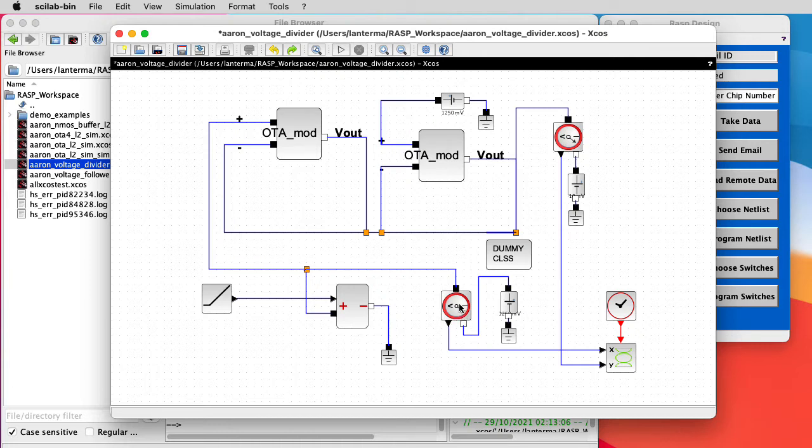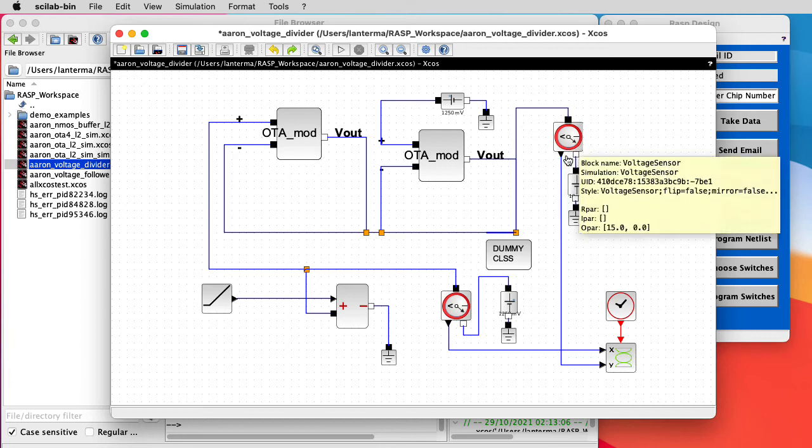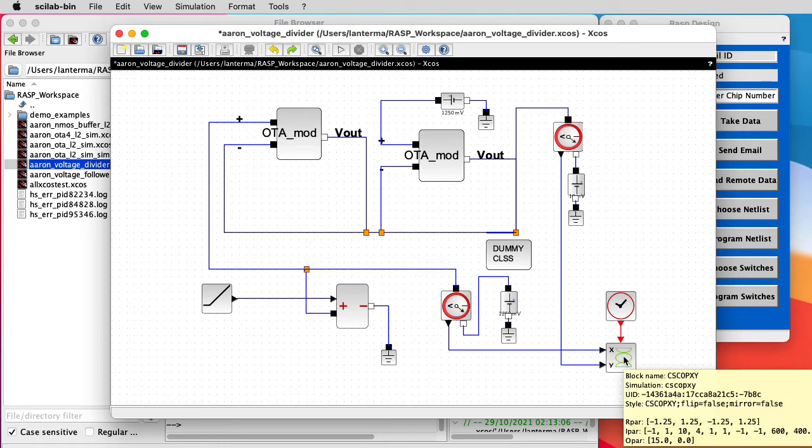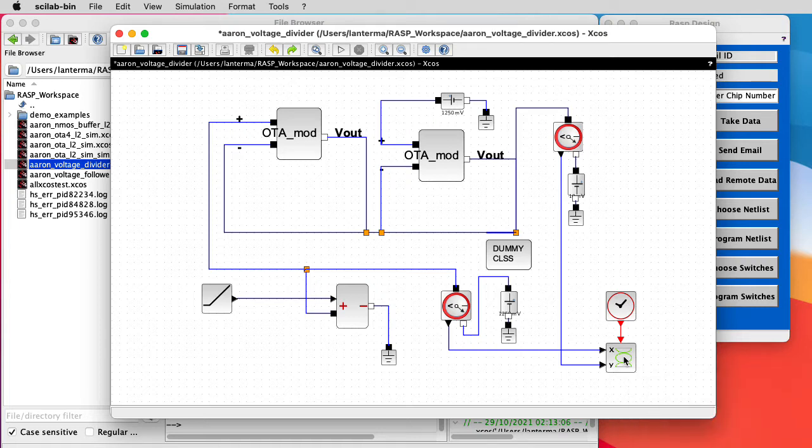Anyway, I have one of these voltage mechanisms for the input and another voltage mechanism for the output, both referenced to that 1.25 volts. So if the voltages here are 1.25 volts, that then is going to show up as 0 on the scope. And I did that just so my plots are all centered at 0. I found that an easier way to interpret the input-output transfer function. Here I mean just the nonlinearity of whatever this function is, the memoryless nonlinearity. I'm not talking about transfer function in terms of a Laplace domain function.